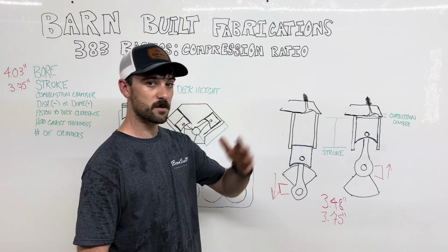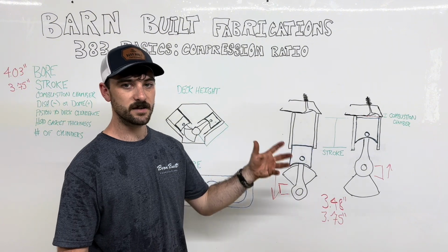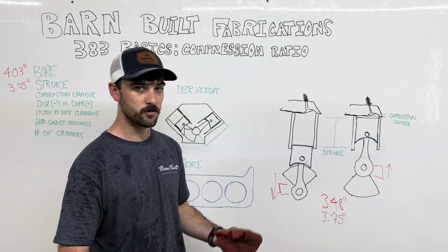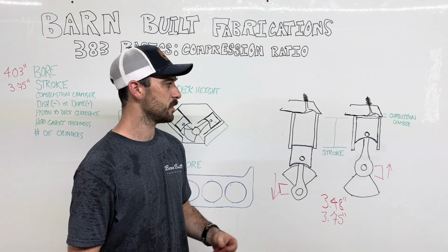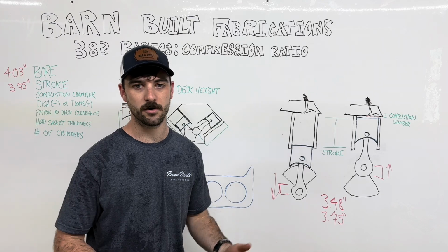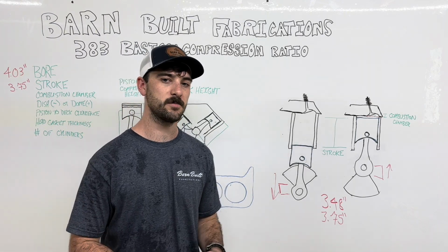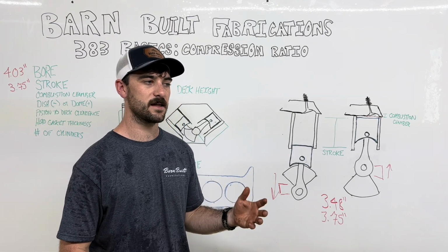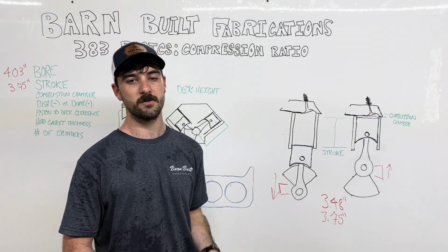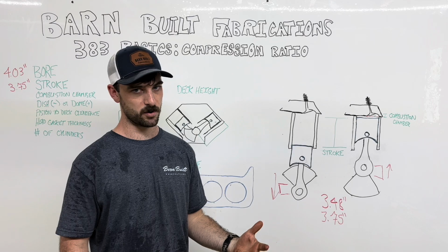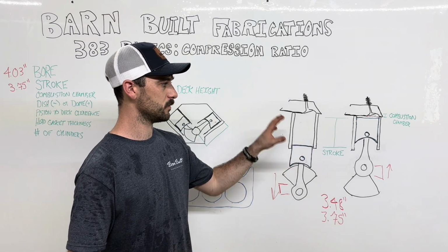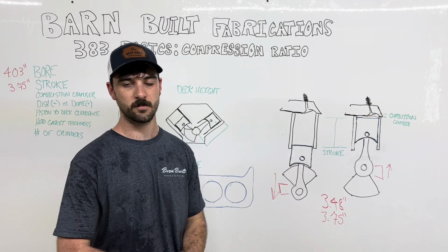And just to talk about the fuel, the octane rating, you see like 85, 87, 91, 93, whatever you have at your gas station, the octane isn't really the power that a lot of people think it is. The octane level is how much you can compress that fuel before it ignites and how long it takes to burn. So those two factors weigh very heavily on detonation and compression ratio.